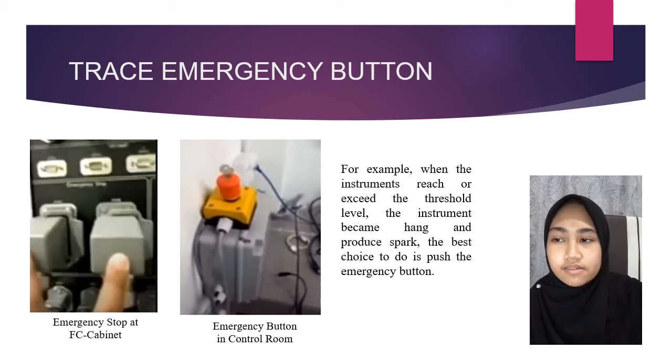Usually, the instrument already has its own threshold level, so whenever it exceeds the limit, it will automatically activate the grounding switch. Shielded cables must be used for the emergency connection. If the second emergency stop is not used, the plug has to be bridged. The emergency stop has to be connected at least one.